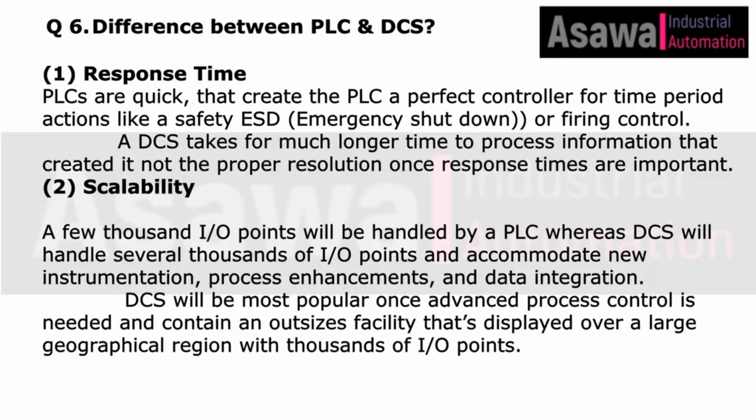Question 6. What is the difference between PLC and DCS? 1. Response time. PLCs are quick. That makes the PLC a perfect controller for time-critical actions like safety ESD, emergency shutdown, or firing control. A DCS takes much longer to process information, which makes it not the proper solution once response times are important.